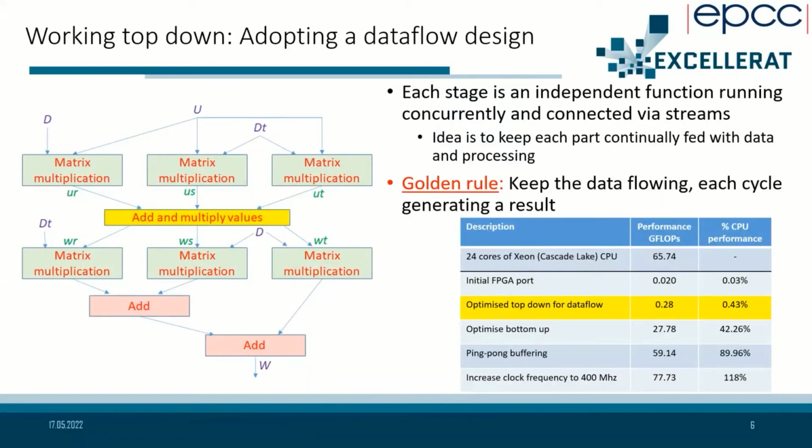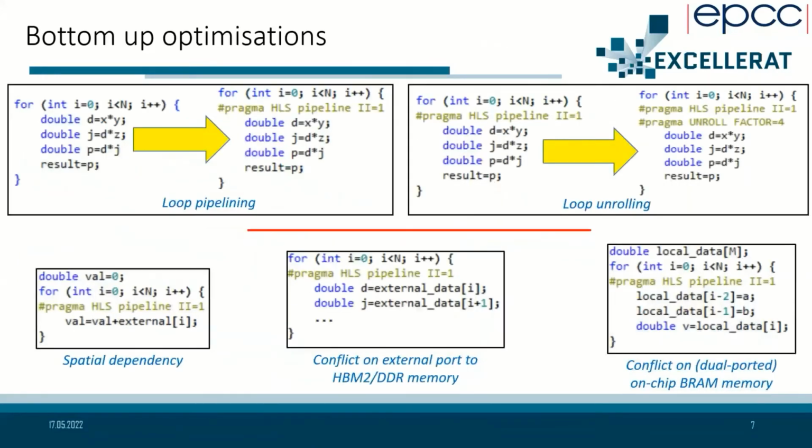And that's okay, but it's not sufficient on its own, because what we also need to do is to go into each of these boxes and optimize bottom up, optimize exactly what's running within each of these independent regions that are there concurrently. And that's where we're playing lots of different tricks, things called pipelining up here, where each of our individual loops are spread out around the logic, so we can feed in a new iteration every cycle and get these things running concurrently.